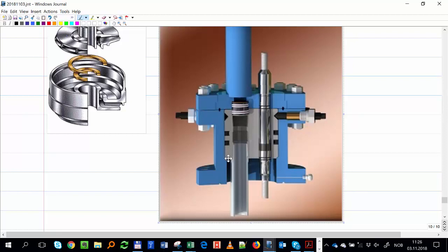The tubing hanger, you see this angle here, is sitting on the wellhead, and all the weight of the tubing is transferred to the wellhead. And then you have this big hole, through which you have the cable that goes to the ESP. So you see, it takes quite a lot of space. If you want to increase the diameter here, you don't have much room. It's not that you have the whole diameter of the casing. It's much less.